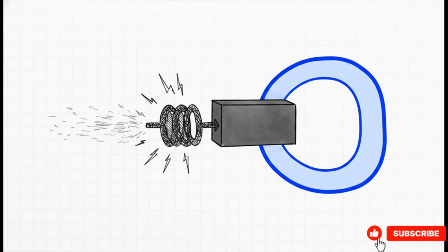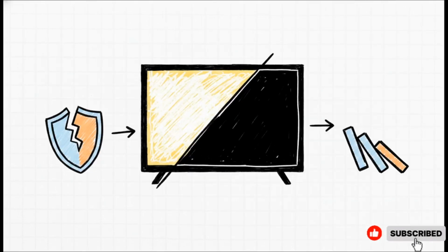See, when you abruptly stop current flowing into an inductor, it kind of panics. It reverses polarity and creates a massive, highly dangerous voltage spike as it desperately tries to maintain the current flow. So this diode acts as a critical safety vent, letting that reverse current harmlessly loop back around and dissipate into the circuit. So what does it look like when this heavy lifting system fails?